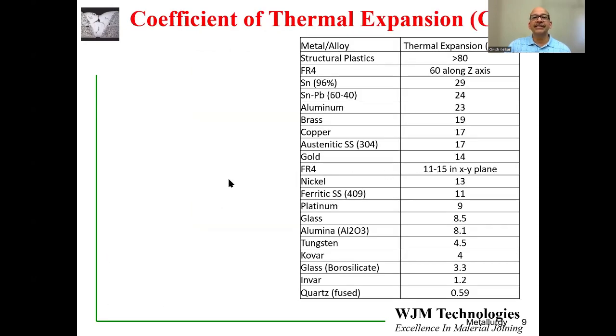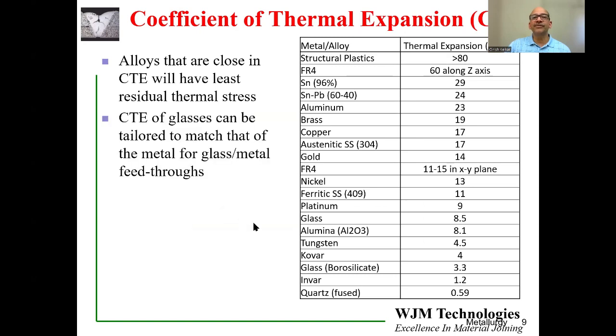Another source of stress is the coefficient of thermal expansion. Whenever we weld dissimilar materials, and that is quite often the case, we are welding dissimilar alloys. Sometimes we are also making assemblies by brazing and soldering, where you have a lot of dissimilar materials. A lot of these welds, joints, brazes and solders are done at high temperature. And as the assembly cools down, it introduces stress in the weld just because of the difference in CTE.